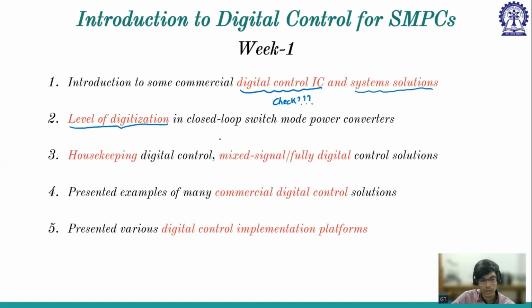If it is like a three-phase inverter, can we use the VMC or CMC there? I'm not exactly sure whether they'll use current mode control, but they'll use this phase-shifted pulse width modulation, which is PWM. So they'll have these PWM signals which are phase shifted because it is for three phase, and there will be a sine wave, and then they'll compare.